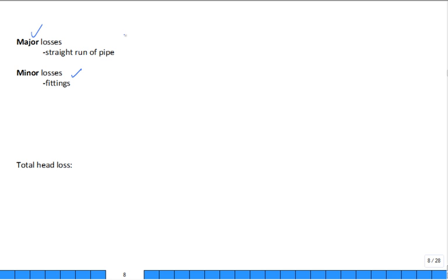Well, here's the equation for the major head loss. If you want to work in pressure, the pressure loss is the friction factor. How would you get it? Colebrook, Haaland, some analytic expression, 64 over Reynolds number if it's laminar flow, or go to the Moody diagram and pick it off. Friction factor, length over diameter, 1/2 rho v squared, the velocity pressure.